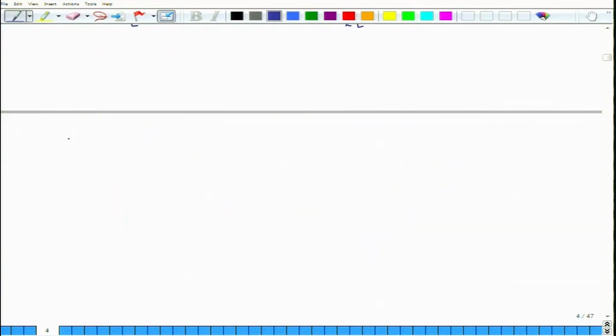So I will say that S11 equals 1 over EL, S22 equals 1 over ET, and S12 equals minus nu LT over EL, or you can also state it as minus nu TL over ET.